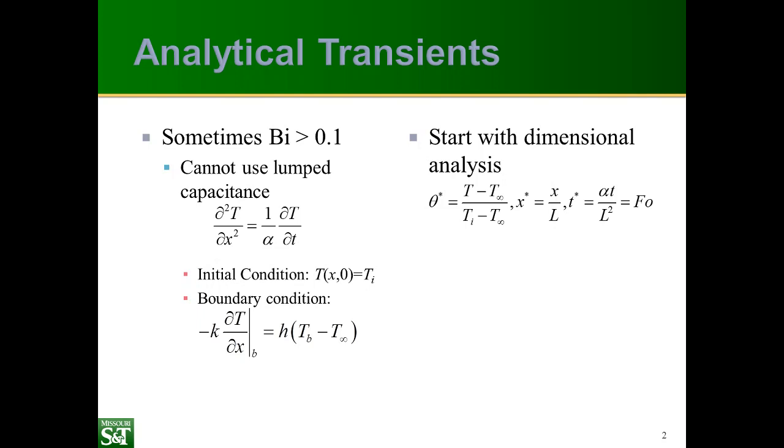We begin this process with dimensional analysis. We look at Buckingham pi to figure out how many dimensionless terms we need, and then we can use the method of repeating variables to figure out our dimensionless terms. So what we can do is reduce the complexity of this problem. So we define our dimensionless terms, and now we have our boundary conditions, right? Our initial dimensionless temperature, and then our dimensionless conduction and convection terms. So this allows us to reduce the problem in the boundary conditions to only 4 variables. We have theta star, x star, Biot number, and Fourier number. So what this means is, as long as you can come up with expressions for those 4 variables, all the solutions will look roughly the same.